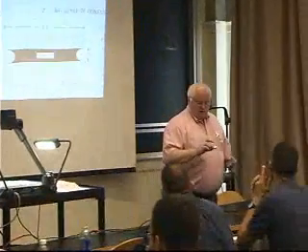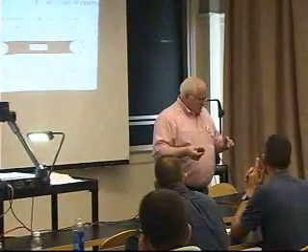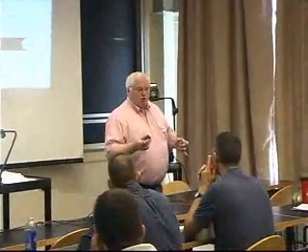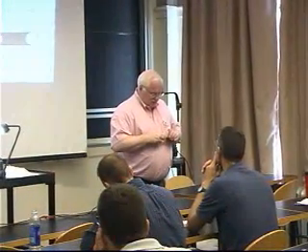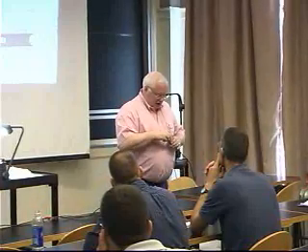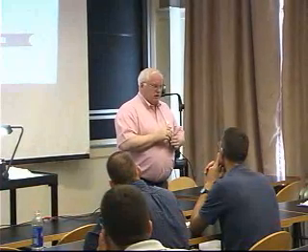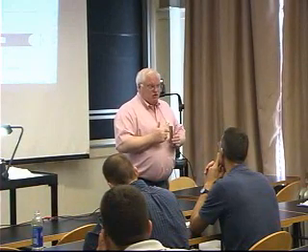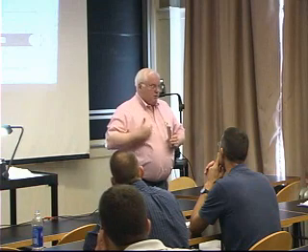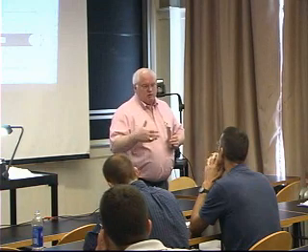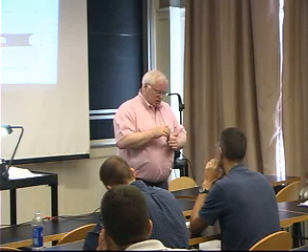But if I'm trying to do something really, really precise, these are two 3-inch Johansson blocks. And the ends of these are ground very, very precise. And I have a calibration traceable to the National Bureau of Standards that says these are 3 inches plus or minus 50 millionths of an inch at 70 degrees Fahrenheit, or maybe 72, whatever it is. I can look at the calibration.